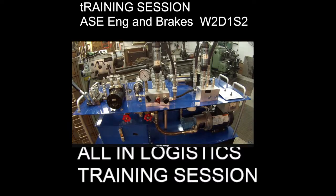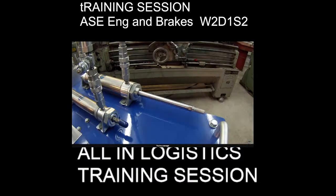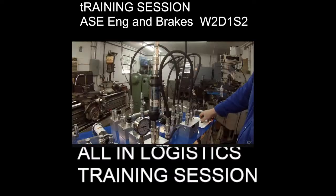So what I just showed is that hydraulics is flow is speed and pressure is force. So what we're going to do is show you that flow slows it down. We're right at about 1.8 gallons a minute. Let's cut that down to about half.